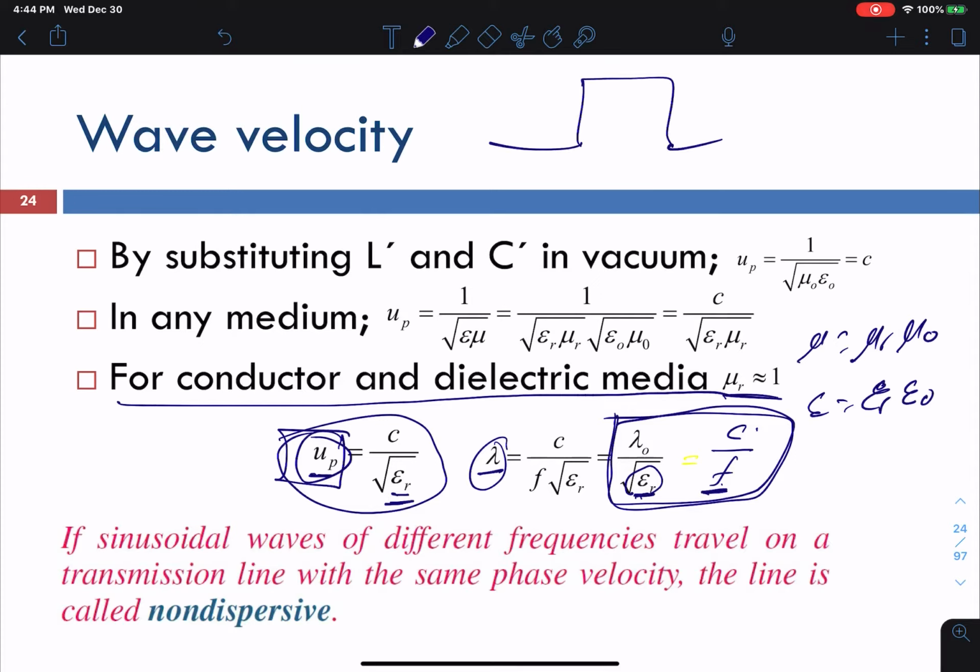Each pulse is made out of an infinite amount of sinusoidal signals, right? So that means each pulse contains a lot of signals with different frequencies. Now, when the pulse goes through the transmission line, that pulse should not be dispersing, because all the signals should be going at the same speed if the dielectric material in the transmission line does not depend on frequency. All right.